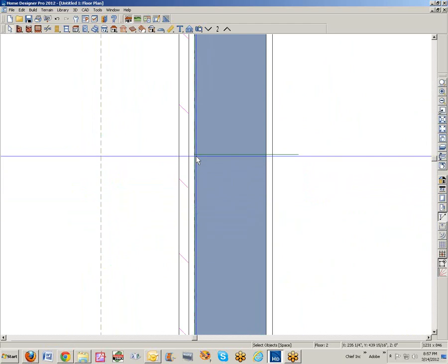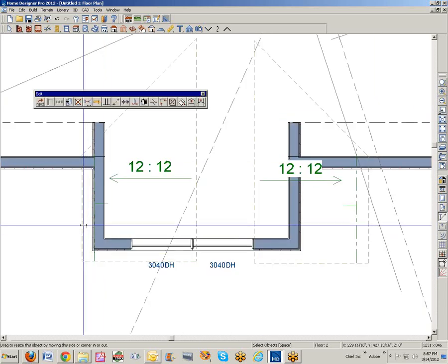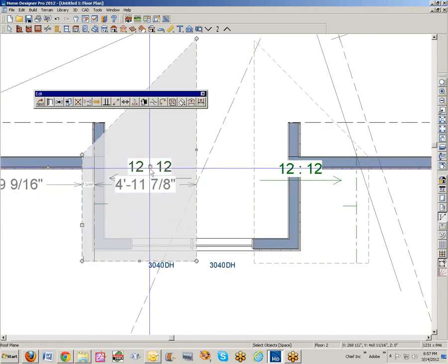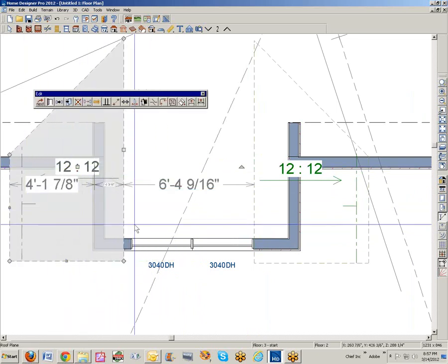That's because engineering-wise, that's where the load bears. All the force coming down from the roof and what's on the roof or what's pounding on the roof or blowing on the roof, whatever, the force comes down right here, and that's why they put the baseline there. There's some specialized conditions, which I'm not going to go into, about where these baselines get placed elsewhere.